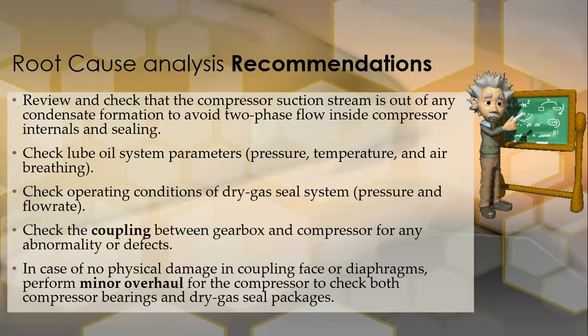We recommended to check the operating conditions of the dry gas seal system, and when they did, we found out that there is a critical problem, as we found that the LEL of the dry gas seal was very high and there were passing gases, and the dry gas seal is suspected to have a problem, that the liquid corrupted it.